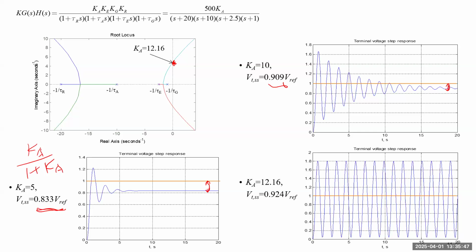The system is operating at a marginally stable condition. And even for this case, the final voltage still has a large gap from the reference value. Which means for this system, as long as there's a disturbance, the voltage will never go back to the original value, if it is a permanent disturbance.